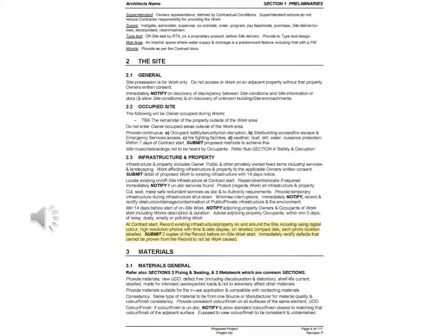Simplicity is also vital. Coming back to the site subsection, an example in infrastructure and property specifies dilapidation reports. Some specifications have the architect, adjacent landowners and the contractor jointly inspecting for defects, finishing with a sign-off. This is a huge undertaking and needs to be simpler. In our spec, the contractor makes a record and any damage complaint is the contractor's responsibility if the report can't show otherwise. Now I know it may seem I'm skipping around.